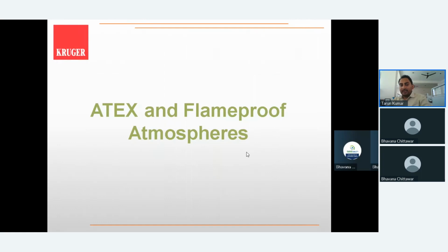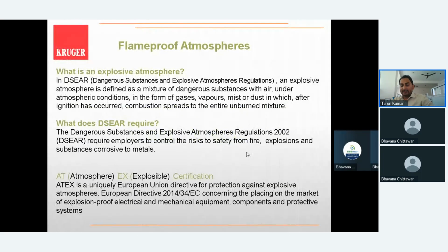Further to that, the ventilation for flame proof atmosphere. There are multiple guidelines given for the explosive environment, with classifications from different bodies. They ask that the fan be ATEX certified. ATEX is the body which will certify that the fan is completely flame proof or spark resistant type.